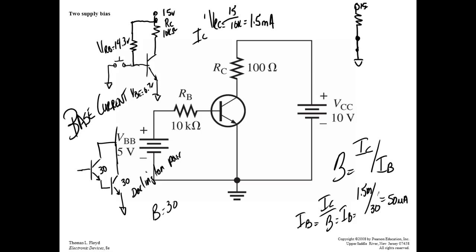We usually don't use this for stereo amplifiers, and we'll look at later on why. But we use this a lot of times for saturated switches, especially if I'm going to let a microprocessor drive something. A microprocessor can't source a lot of current, but this, it doesn't need to source a bunch of current, right? What's this called? Can y'all read it? Darlington pair. It's called a pair. You run them in pairs. We'll talk about some more advantages of that.